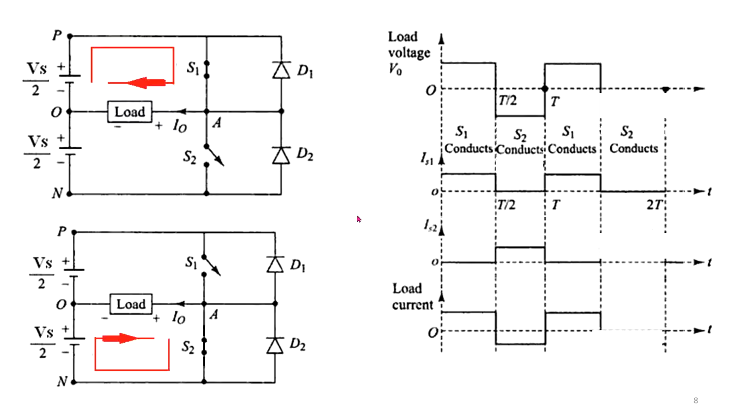And let's go back to the next cycle, which also follows the same direction. Come back over here, you will see this is the direction we are looking at. The load voltage is inverted, but the current through the switch is the same. That's why it appears to be the same. Okay, and however the load current is inverted. Now you can clearly see the inverter operation in this case.